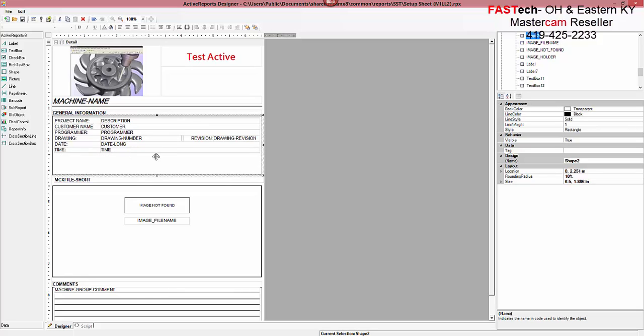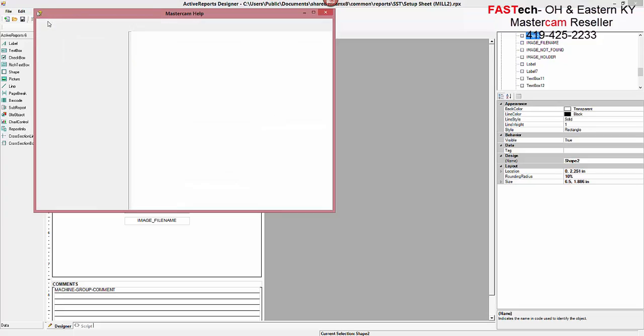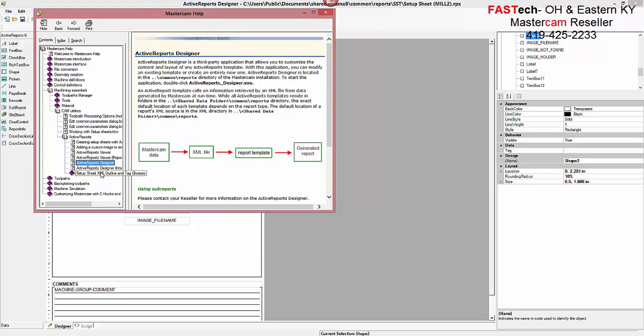Now, if you're not familiar with XML tags, it can be a little bit confusing where they're located and what definitions are where. You can simply go to the help function. It's up at the top. Grab the setup XML, and we're working under mill and router.